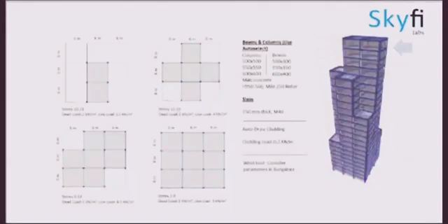Design using ETABS, considering wind load parameters in Bangalore. By looking at this figure, we can see the various beams and columns that have been given, and we have to use the auto select option for both beams and columns of various sections, considering M40 concrete, HYSD 500 and mild 250 rebar, and the slab as 150 thick. The various sections and grid lines as shown in the figure have to be constructed.